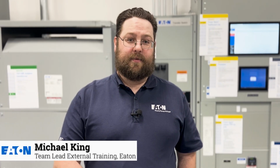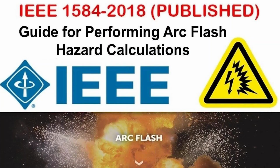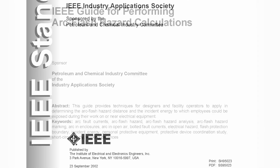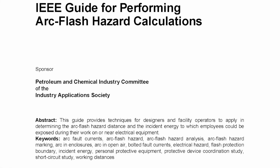An arc flash study is that requirement from 70E to choose the appropriate PPE. We need a calculation as to how much energy could be released. And that ties really back into another standard that's IEEE 1584. Most of us are familiar with the 2002 version of 1584, which was really the first standard where we had good test data. And when they wrote that standard, they tested equipment, they actually blew it up in labs and measured how much energy is released during an arc flash.